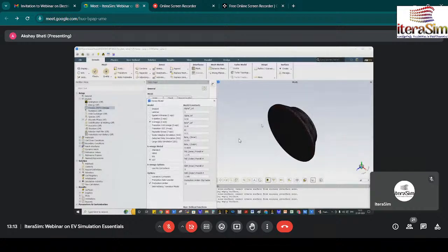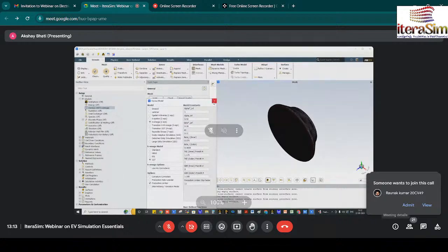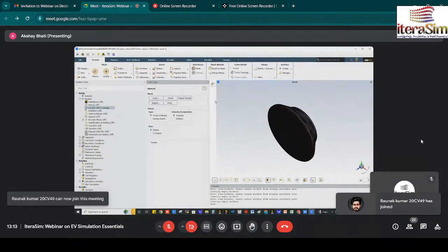But k-epsilon model doesn't capture the boundary layer effect. After that, k-omega works in two ways. Near the wall it will capture the boundary layer effect, it will solve the viscous sublayer from a laminar point of view. But as we go further from the boundary layer, it will solve using the k-epsilon model. So it has both effects, so it is better, though it is a little bit computationally intensive. But it is better to use the k-omega SST model for a fan.